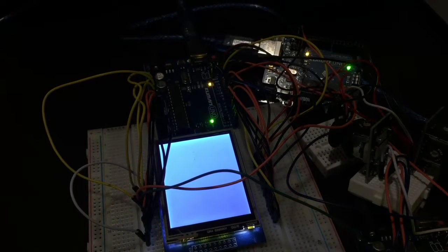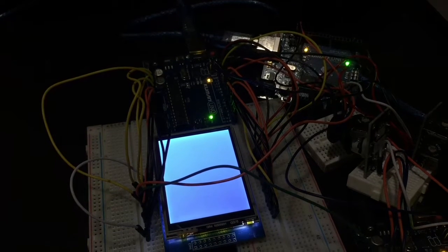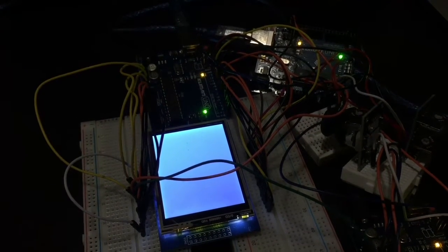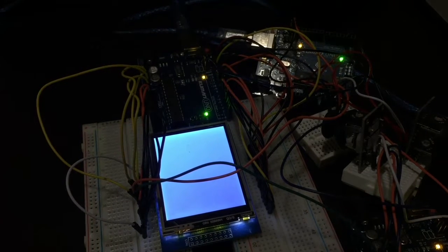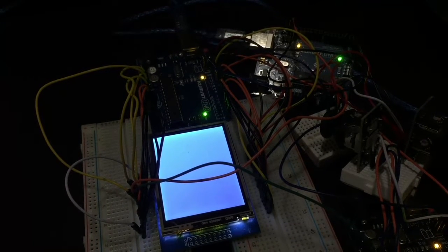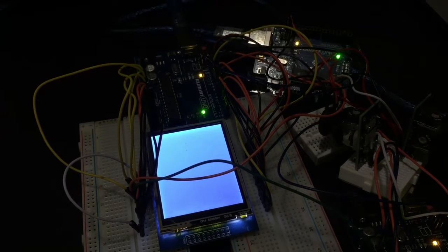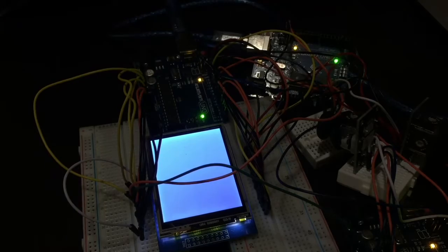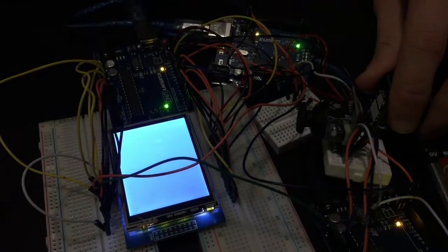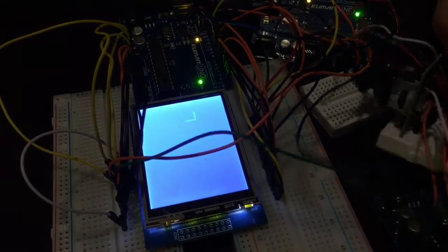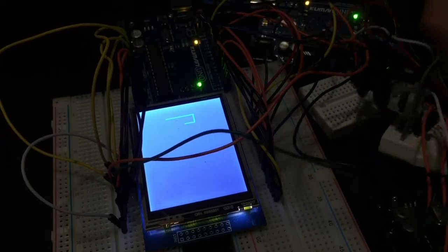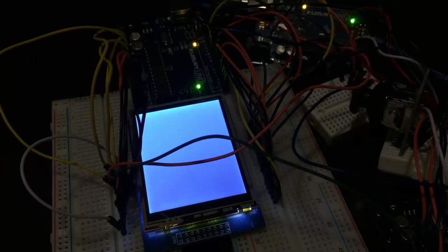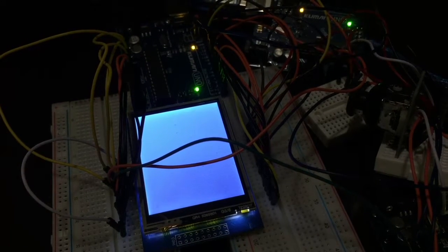However, we quickly ran into the issue of memory constraints. The Arduinos just don't have enough memory to hold all these values, and they were segfaulting very quickly, running out of space. And so we had to throw that idea out. We resorted to just having it so that each Arduino has the capability of deleting the entire display, as this is the only viable option.